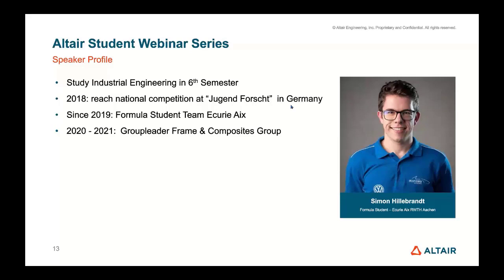I think I can answer that very quickly, just off the cuff. When you want to simulate any sort of aerodynamics, you're normally just looking for the flow profile that goes around your structure. So whether it's filled or not, I don't think it matters, because you actually just need to see if there are any trapped vortices around those areas. Hence why it's very important to get the correct surfaces and make sure that your geometry is properly enclosed. So you can fill it with foam, you don't have to.